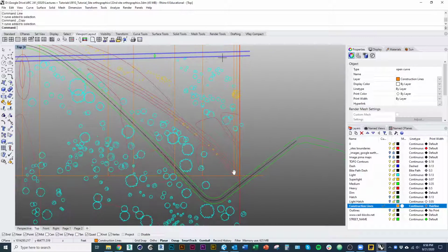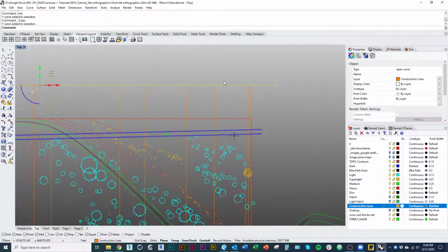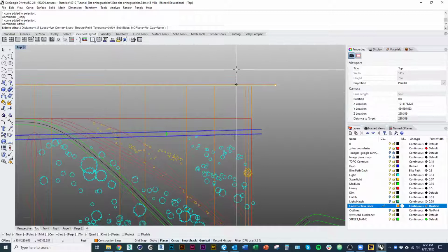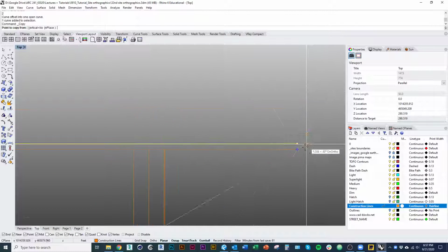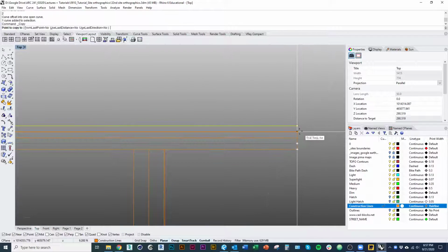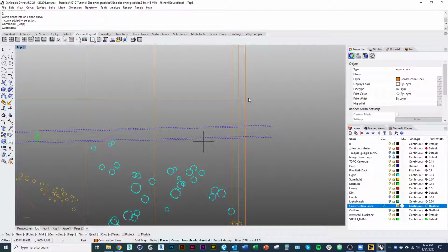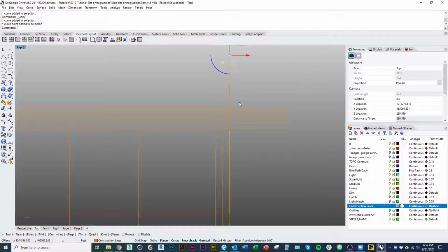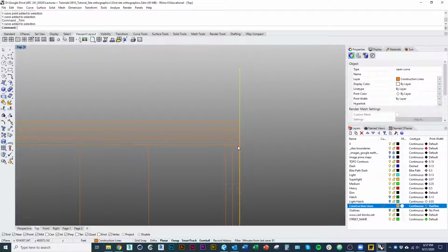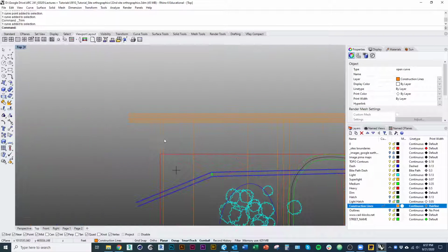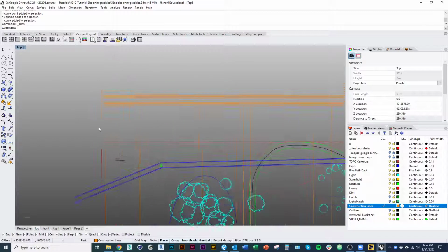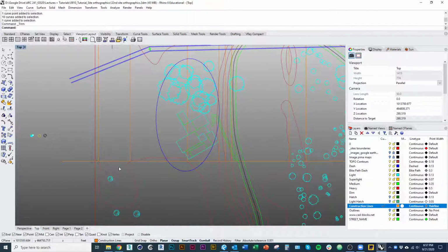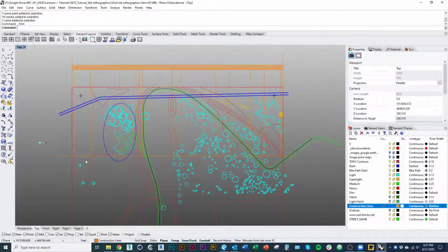And so, let's see, low point. So I'm going to start offsetting this line. I go 2 feet. Do it a few times. Once you've offset it once, you can just copy it, and then use the previous line. It's 2 feet apart already. There. Grabbing that point and moving it up. Trim the excess. Okay. So I don't honestly know whether this side is lower or this side. I'm just going to start here.